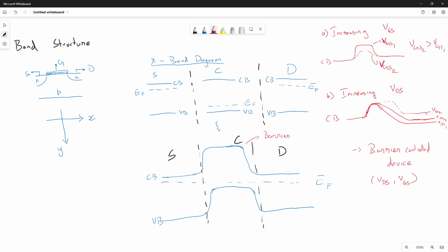Because there is a formula, V equal to minus Q something. Whenever we are applying voltage on the drain side, the Fermi level goes lower. That's why I'm saying VDS1 is large compared to VDS3. If the voltage is increased, this level has to go down, correct? So if it is going down, the lowermost must have the highest voltage, right? Yes, you're correct. The formula is minus Q times the applied voltage, which is why increasing voltage takes the energy lower.